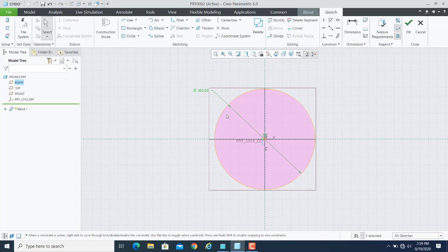So here, suppose I want to divide this circle into 4 points, so you can always go to the edit menu, and in the edit menu, if you look, you can find that divide option. So it is available. The divide command basically divides any segment into the desired number of segments that you define. If I hit the divide key, it will ask you to pick a point on that circumferential area.